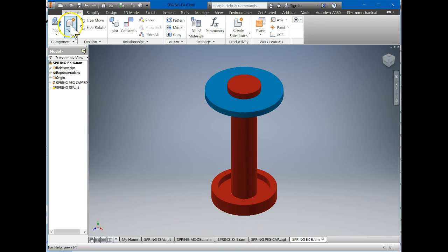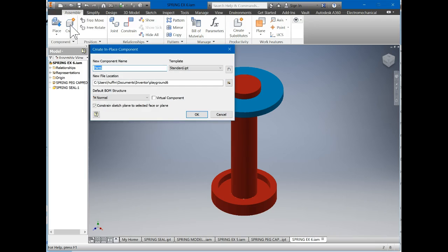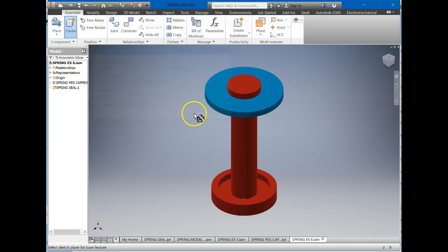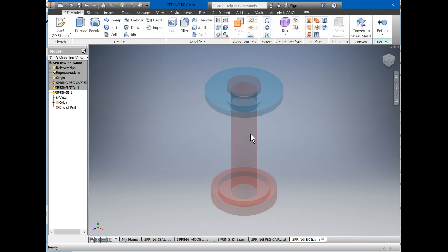We're going to create a part based on this. So I click create part. We're going to name this spring, not pring, spring. And I've done a few of these, so I'm going to call it spring 8. But you can name it something that you like. We click OK. And now I have to click on this assembly. And you see that the assembly turns clear. Oh, it's terrible. Whatever are we going to do?